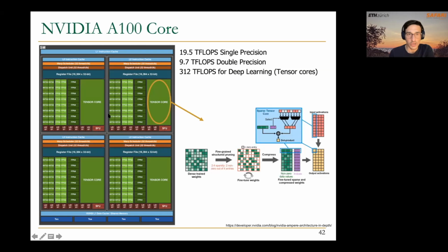In this particular part of the figure, what we have is 16 32-bit integer ALUs, right? And these are also pipelined. We also have these tensor cores here that are a different type of execution unit. And as we will see at the end of this lecture, they are also SIMD units as well.